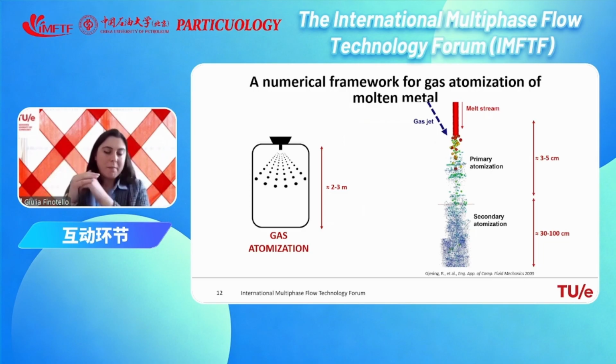really when the melt is just at the outlet of the nozzle. So yeah, definitely several dynamics are happening there, and from the industrial point of view, what you want to really avoid is any fast cooling of the melt when it's still not broken up in the form of smaller droplets and then particles.